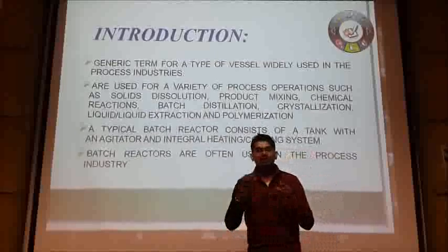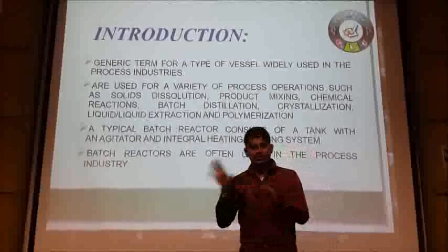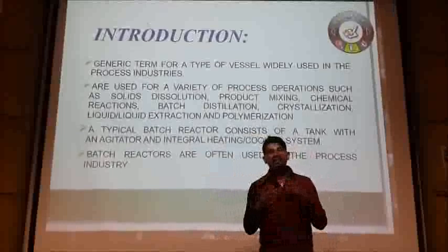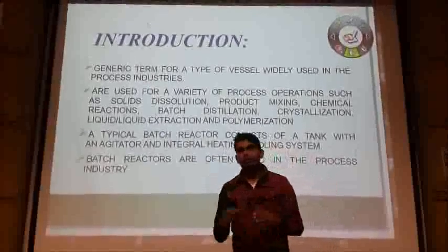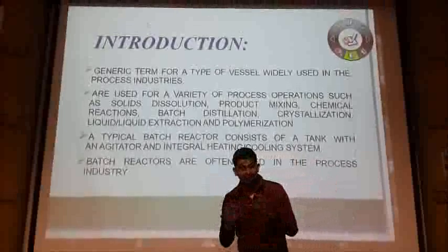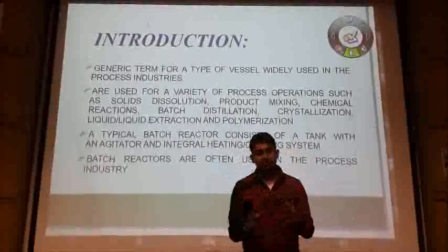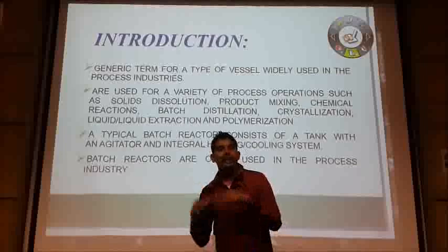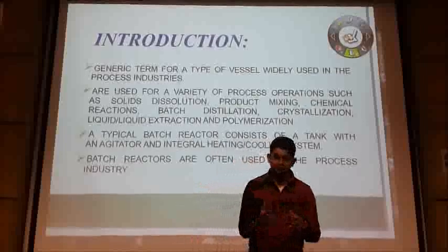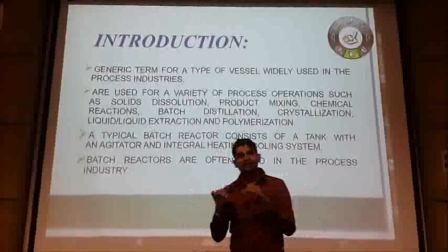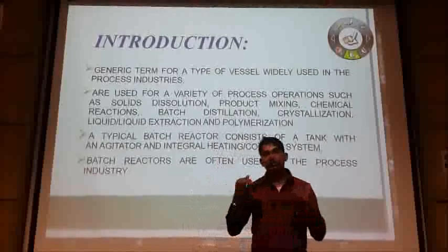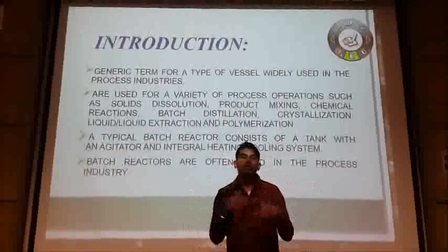The heating and cooling system, that's it. In order to maintain the reactant content, you need a desired temperature, so you need heat. So a heating or cooling coil or an external jacket is used for heating and cooling the reactor. The heat transfer fluid passes through the reactor, helping to add or remove heat.